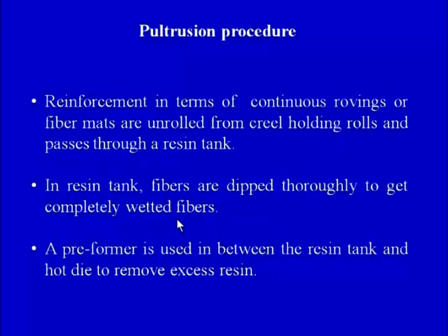So resin has to have the viscosity so that it is able to wet the fibers completely, so that none of the fibers are left dry before entering into the preformer. So each and every fiber should get wet during the process of the resin bath. When the fibers are going through the resin bath or the resin tank, they should take the resin along with them, and each and every fiber should get wet.